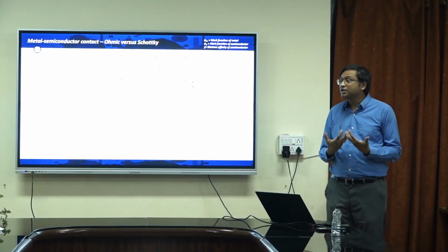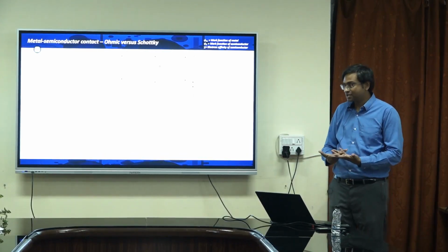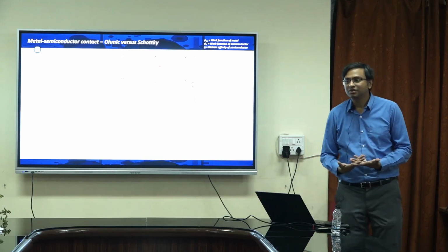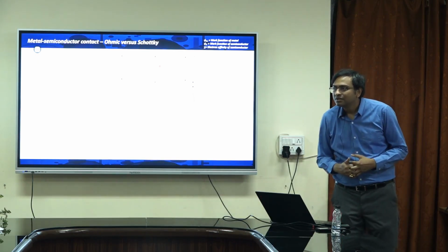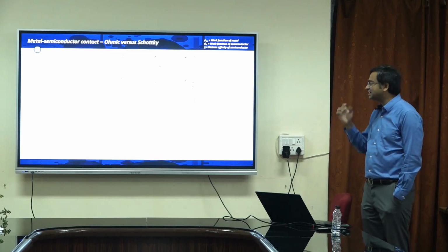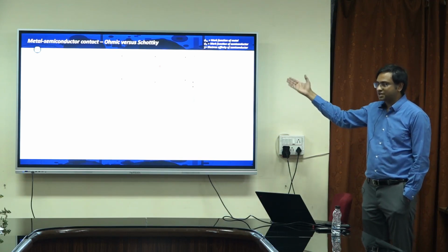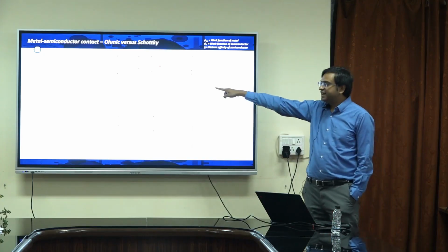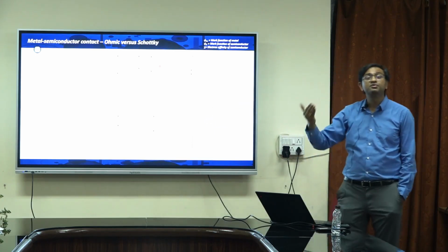So if I wanted to make an ohmic contact for hole injection, what kind of work function of a metal should I choose? No, no. Ferroelectric is not a metal at all. Ferroelectric is a different set of material. We are talking about metals. A smaller work function or lower work function. Like you saw in the previous thing, what did we choose for an n-type material? A smaller work function metal. Phi m is small. What should we do for a p-type material?